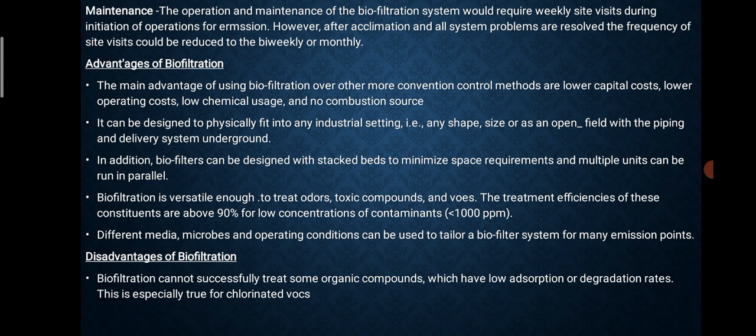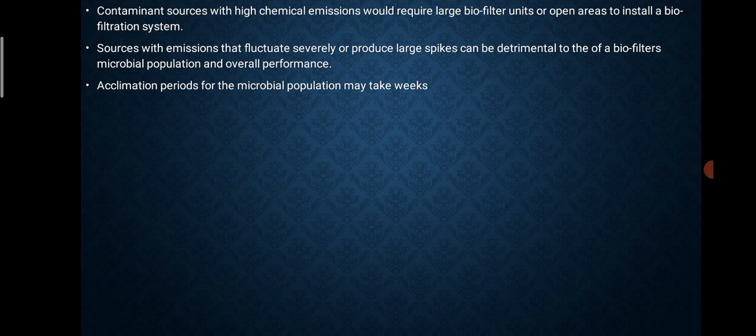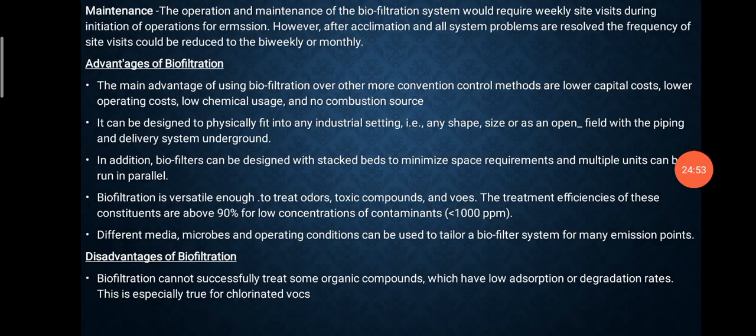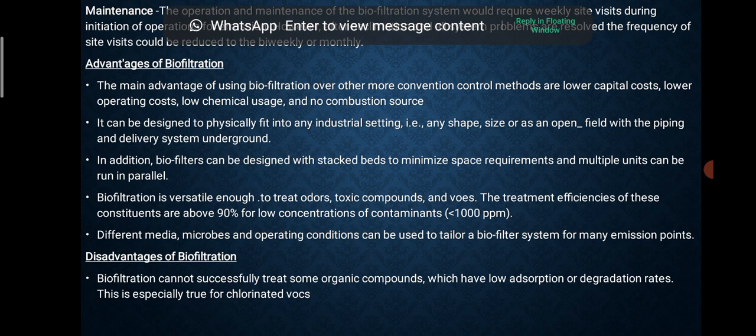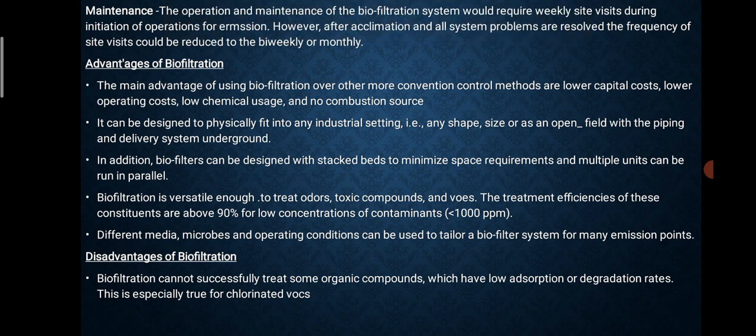Advantages of biofiltration. The main advantages of using biofiltration over other methods is it is more convenient to control low concentration VOCs and lower capital cost, lower operation cost, low chemical usage, and no combustion source.